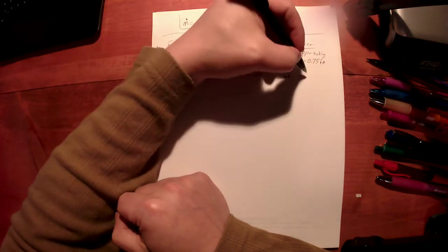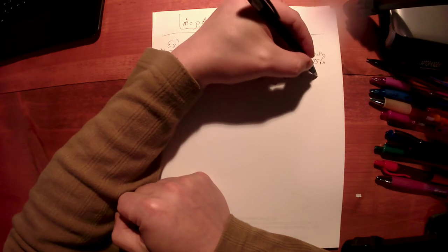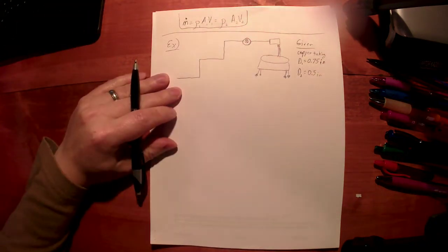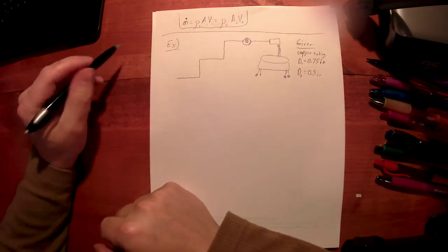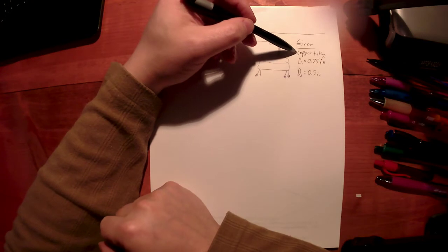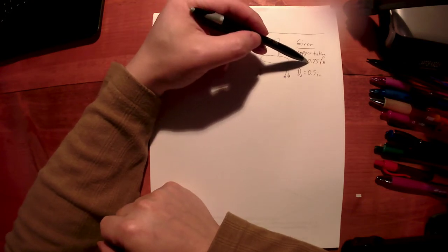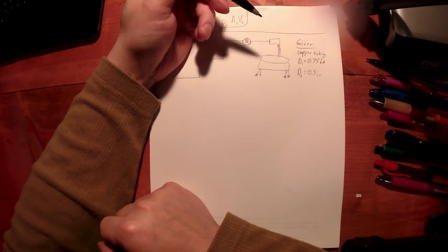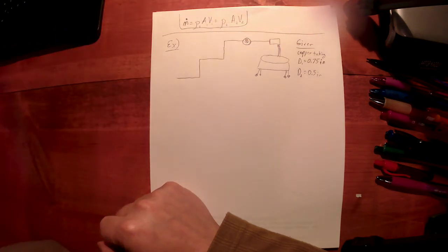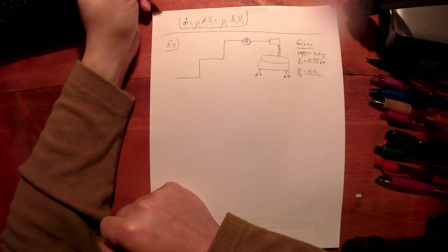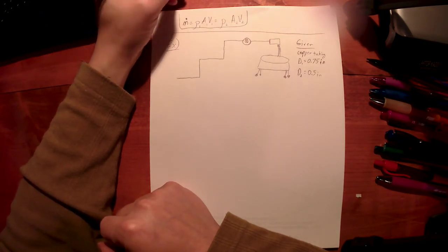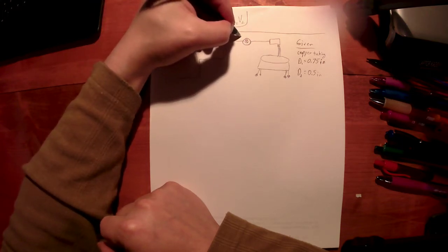We'll say that diameter is a 1/2 inch. So it's coming out of a 1/2 inch diameter outlet, but the tubing itself, we're going to say, is nominally 3/4 inch. Now, it would be worth our while probably to go look up for copper tubing nominally at 3/4 inch what the actual inside diameter is going to be and use that to find our areas, but we're going to keep it simple here and we're just going to assume that we can use this nominal 0.75 inches as our value.